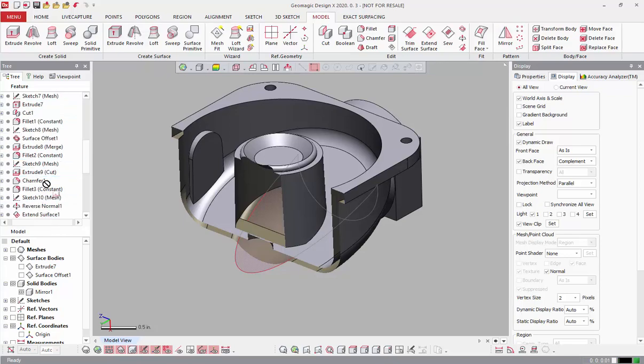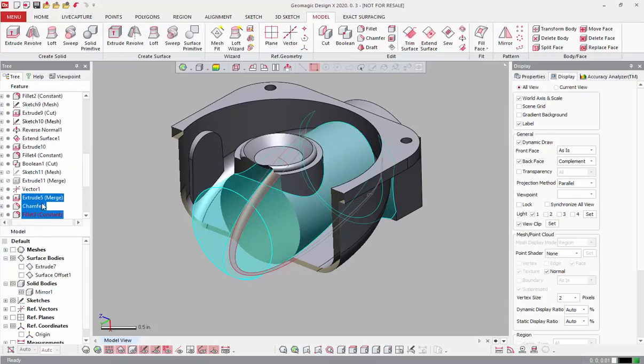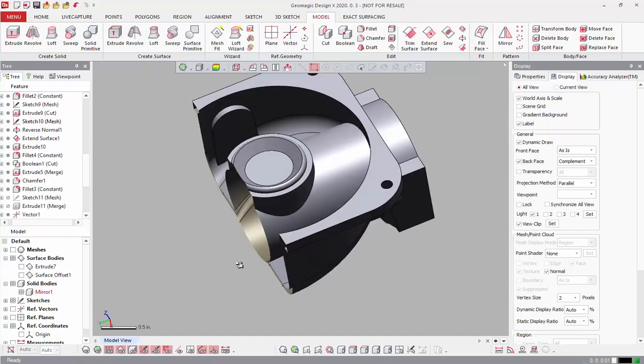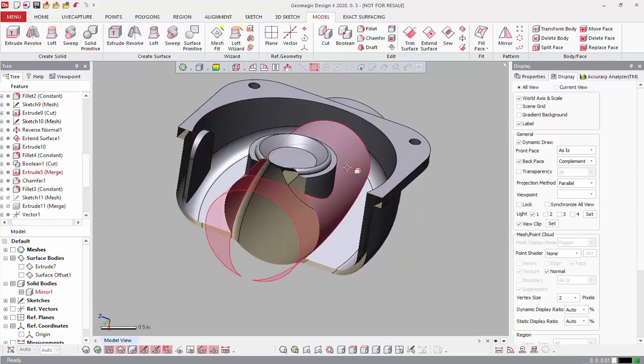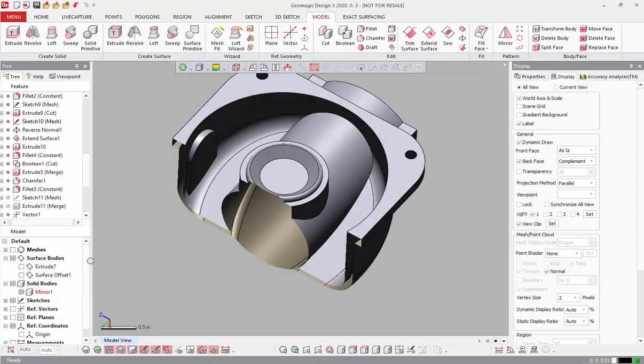Nope, I've got one child entity, which is that chamfer, which makes sense. So I actually need to move both of these features down now below something, and it's not letting me do it. Oh, that's fillet actually is also something. So let's see if I can move all of that down below the cut. Oops. Just below the cut is where we need it. There we go. And so I've rearranged the feature tree there, right? And allowed for this cylinder to exist after cutting this area out.